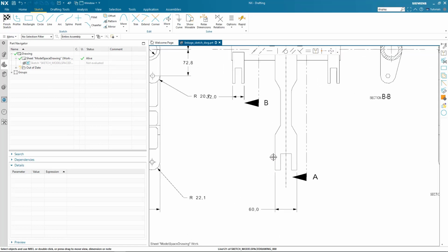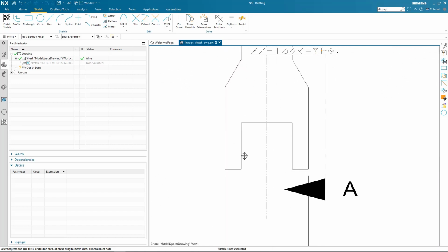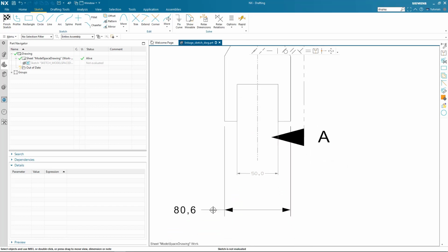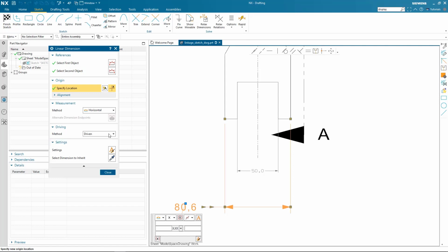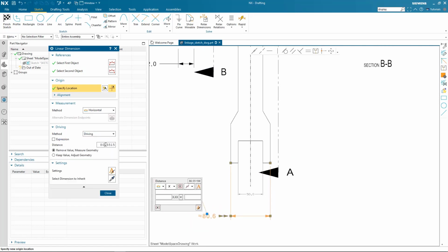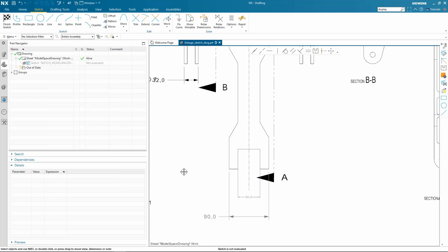So now that we've made those lines symmetric, we can simply just drag and make them bigger. One other nice thing we can do now with the new sketch is we can add dimensions to get the nominal values we need. In this case, we want this notch down here to be 50 millimeters. Now on the dimension that came across from the original file, what we'll do is make that a driving dimension instead of being driven. What that'll allow us to do now is to type in a value and control the width of those lines. You can see now we've done that.